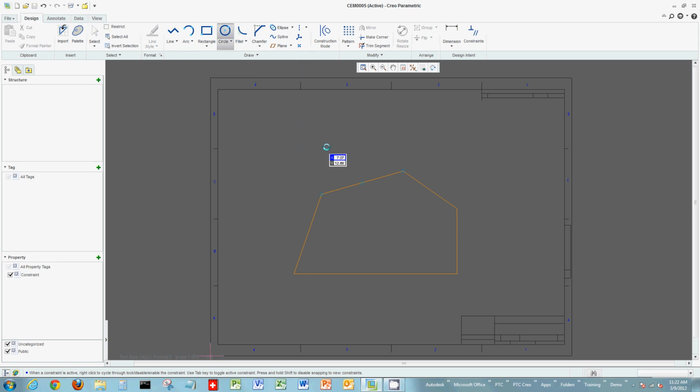Also, for movement of other elements, again, you can use the alignment constraints, drawing an entity. In this case, what you're doing is very similar to other 2D drawing tools. You're actually adding dimensions as you sketch. So in this case, maybe I want this radius to be 0.5. I can key in 0.5, and now it's the radius of 0.5. If I want to move this circle, I can go to the center of the circle, grab it, and snap it just by moving it to another endpoint.